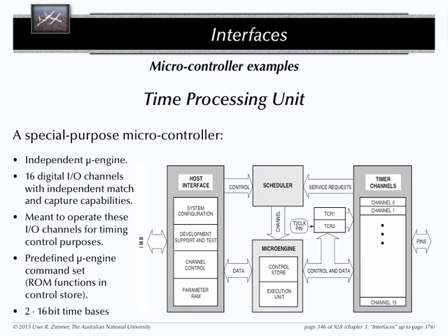It has a hardware scheduler. That's interesting. So you don't have to write your scheduler in software, you have a scheduler already provided for you. In fact, you have 3 schedulers because you have 3 real-time processing units already provided for you in hardware. And they can work on 16 channels per time processing unit, and there are 2 time bases which are dedicated and only accessible for the TPUs, not from the main CPU, exclusively used for those.